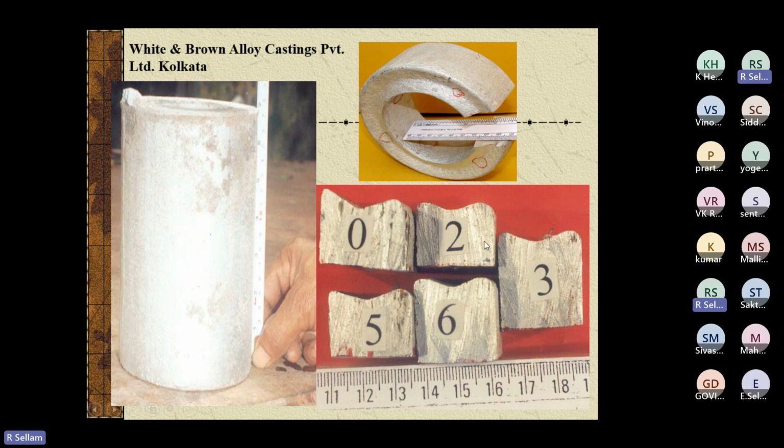While you treat with electric current, see both sides are rounded, because both sides are detached from the mold wall during casting, and solidification takes place without contact with the mold wall. It is separate from the mold wall and solidifies. All the electric current treatments show the same result, and the extent of shrinkage is reduced.